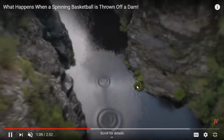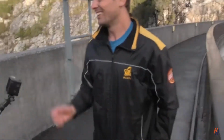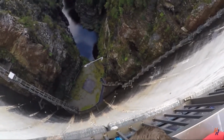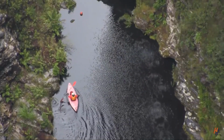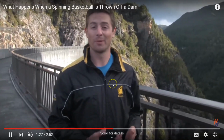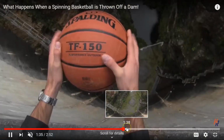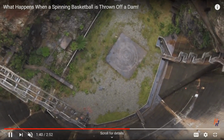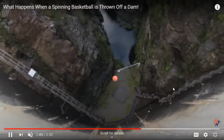Did you see the huge difference? Instead of going straight down, now it is completely curving and going somewhere else. It goes to the body of the water. Completely different. So it significantly changes the trajectory of the particle, just by giving it a little bit of spin, because spin creates a huge amount of force, a lift force, which in this case we call the Magnus force. So you see the difference between this one and this one.